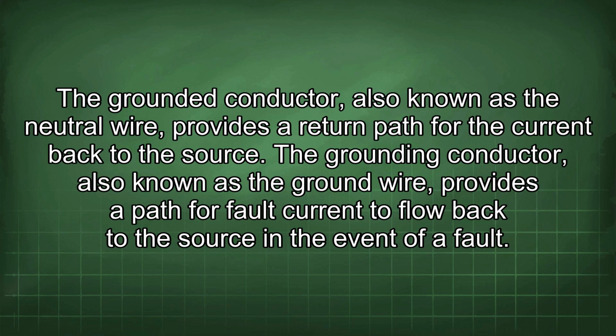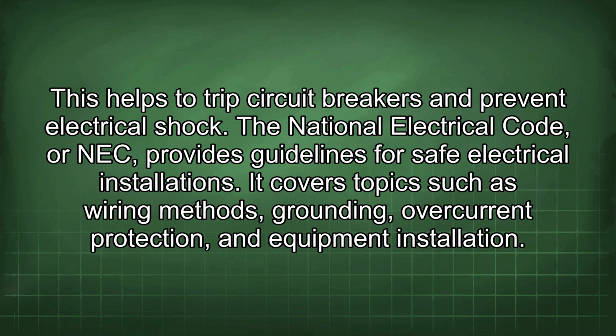The grounding conductor, also known as the ground wire, provides a path for fault current to flow back to the source in the event of a fault. This helps to trip circuit breakers and prevent electrical shock.